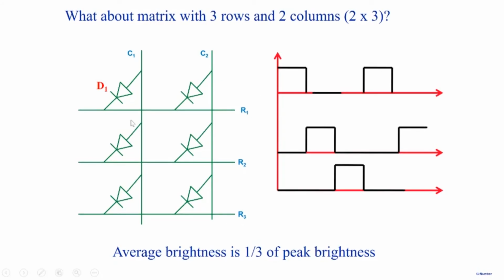Passive, because in electronics we use the term active to denote a transistor. And when circuits don't have a transistor, we generally call them passive circuits. So in this circuit, we don't have any transistors, so it's a passive circuit, and we call it a passive matrix display. Display is obvious, matrix because we've arranged them in the form of rows and columns, and passive because it does not contain any transistor anywhere in my display device. So that's why it's called a passive matrix display.